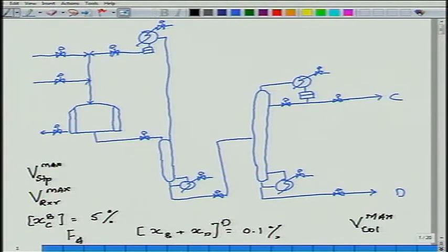Also T reactor reaches its max limit, and the order is first T reactor becomes active and then boil up reaches maximum. As I am jacking up throughput, reactor temperature becomes maximum, and so on and so forth.